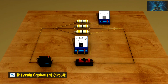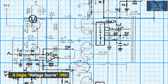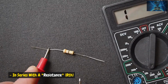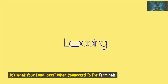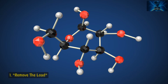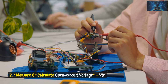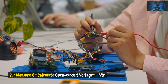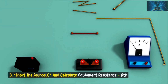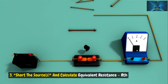Thévenin equivalent circuit. A Thévenin equivalent replaces a complex circuit with a single voltage source, VTH, in series with a resistance, RTH. It's what your load sees when connected to the terminals. How to find it? 1. Remove the load. 2. Measure or calculate the open circuit voltage, which equals VTH. 3. Short the sources and calculate the equivalent resistance, which equals RTH.